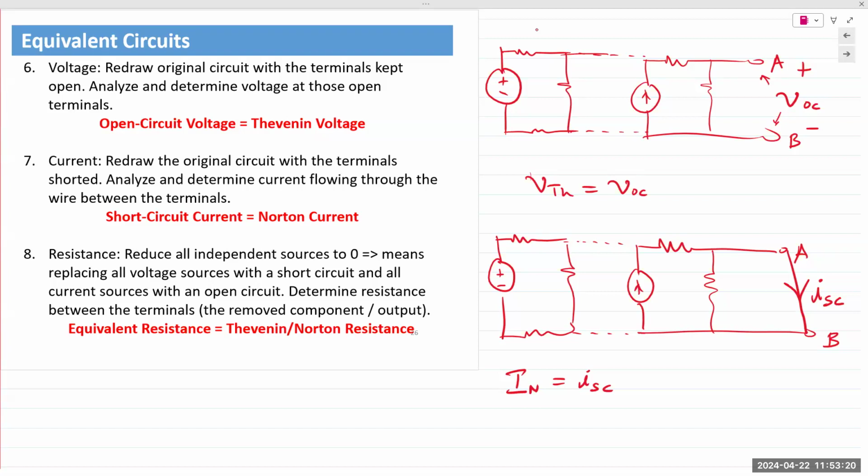Because we place a wire between those terminals, the circuit changes. If there's anything connected in parallel to that wire, it'll be shorted out. Even if there's no component connected, let's say I call this Rx. This Rx resistor is in parallel with the short circuit wire. So that changes the circuit completely. With or without Rx in there, the circuit still has changed, right?